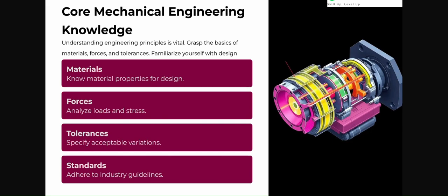For example, 3D printing. In 3D printing there are plenty of technologies like FDM, SLS, SLA. Each will have different tolerances, like plus minus 0.5 mm for FDM, maybe. Similarly, in plastic injection molding, the tolerances will be different, because this process is different. So you should know these tolerances also, right?